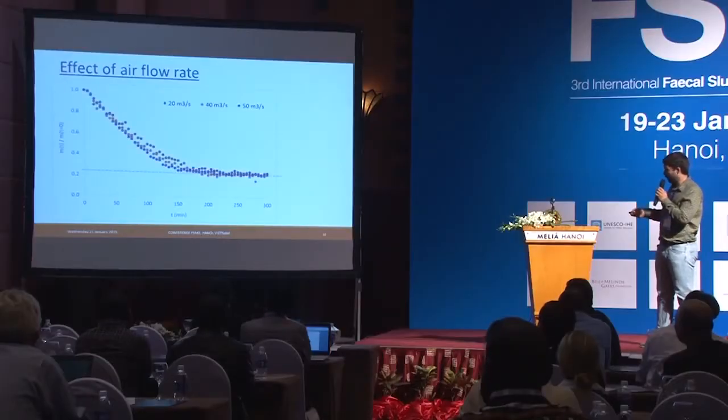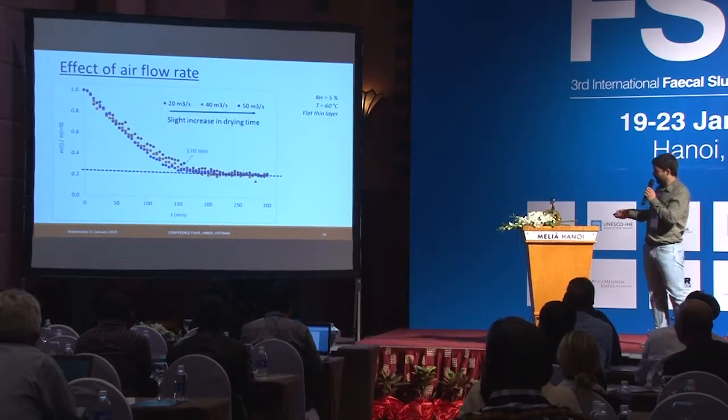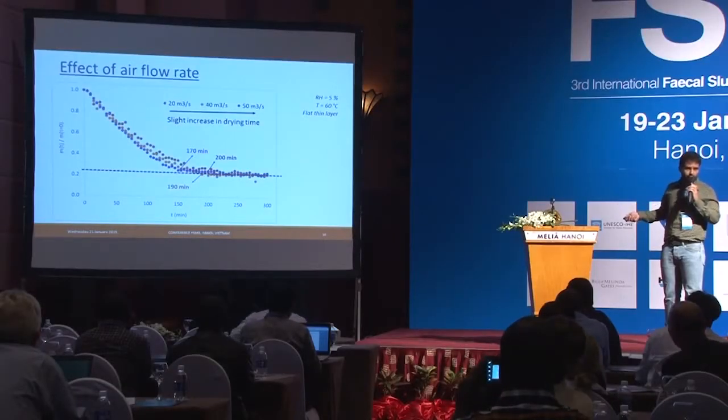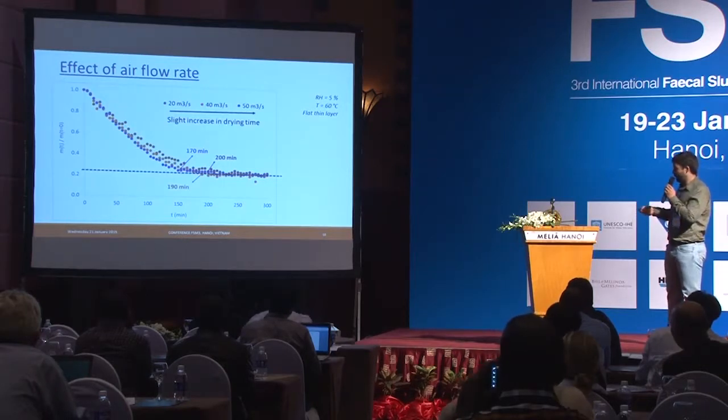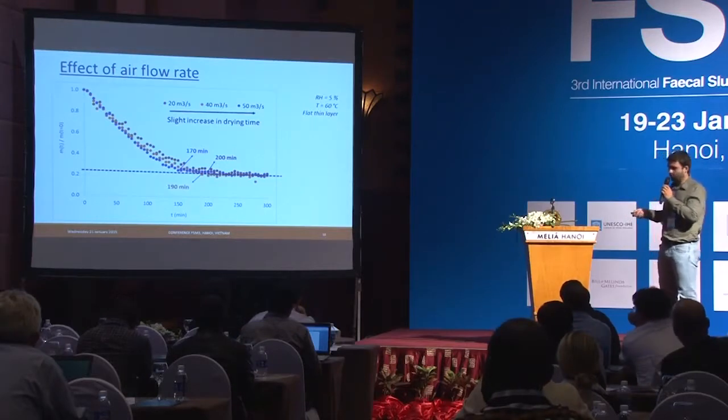Then we are going to introduce the effect of the airflow rate. So I varied three different flow rates. And here are the drying curves we have obtained. And we can see that increasing the flow rate leads to only a slight increase in the drying time. With respect to the other cases, the temperature and the relative humidity, the effect of the airflow rate is slight, lower than the other parameters.